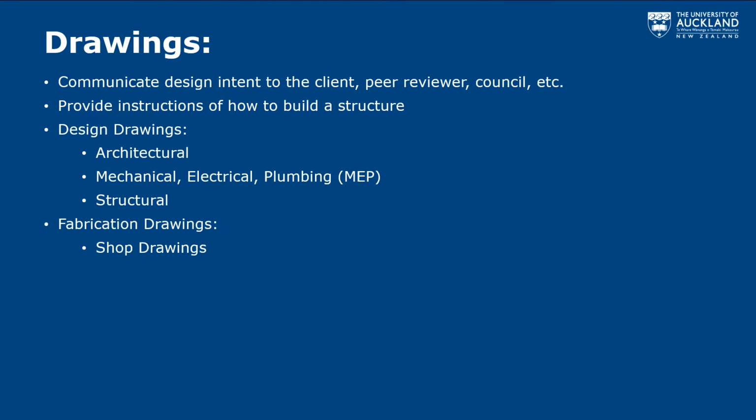But this is essentially a set of drawings which sits in conjunction with the structural drawings. If the structural drawings give you the overview and the details of what might need to be built, shop drawings are, particularly for steel construction, what you need if you have a beam that comes in with holes in the end and stiffeners in it. That's a lot of information to put onto a structural drawing, which gives an overview.